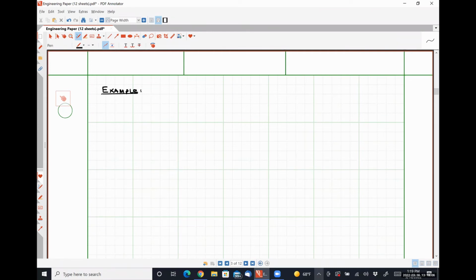We are making an assumption there that the amount of collector current that's flowing through Q1 is roughly equal to the amount of collector current that's flowing through Q2, which means that our transconductances GM1 and GM2 are the same or very close, and beta 1 and beta 2 are also the same. So we're making a hell of a lot of assumptions there to get to that result. The short circuit transconductance is just GM1.